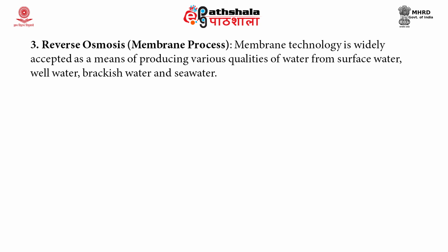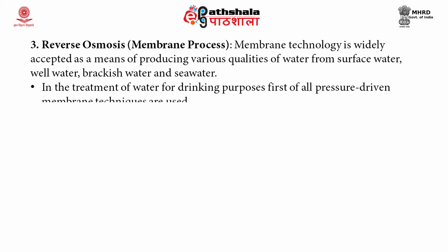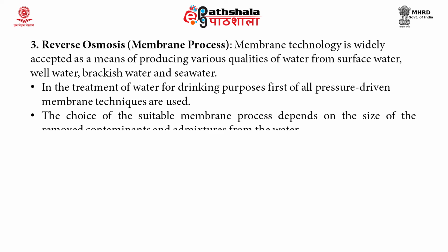After this ion exchange process, another method for the softening of water is the membrane process, commonly known as reverse osmosis. Membrane technology is a widely accepted means of producing various qualities of water from surface water, well water, brackish water and sea water. In the treatment of water for drinking purposes, pressure driven membrane techniques are used first. The choice of the suitable membrane process depends upon the size of the contaminants and admixtures to be removed from the water.